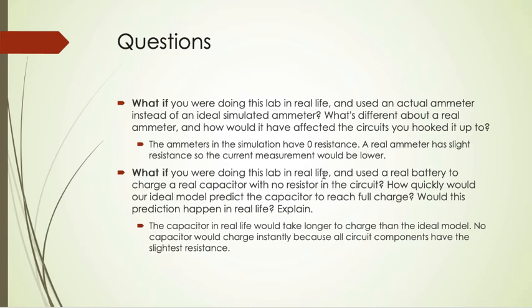And what if you were doing this lab in real life and used a battery to charge a real capacitor with no resistor in the circuit? How quickly would our model predict the capacitor to reach full charge? Would this prediction happen in real life? In the ideal model, the capacitor would reach full charge pretty quickly, but a capacitor in the real world would take longer to charge than the ideal model, because no capacitor would charge instantly in real life, since all circuit components have the slightest resistance.